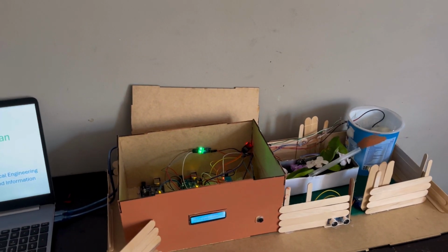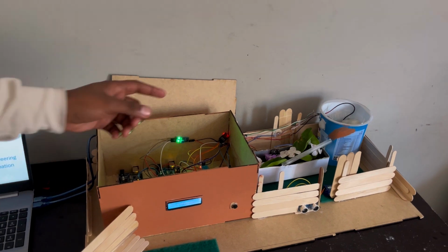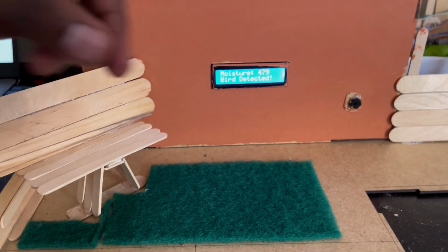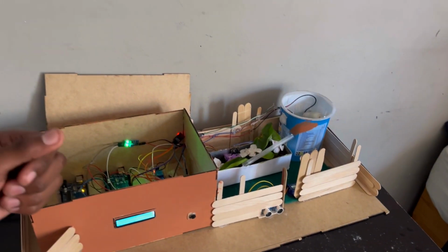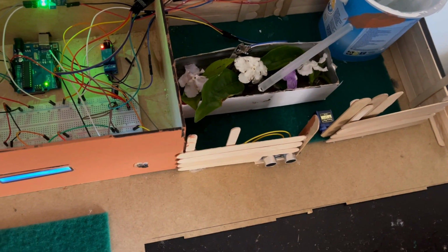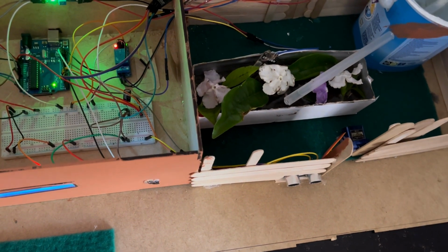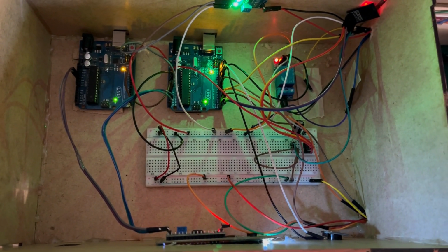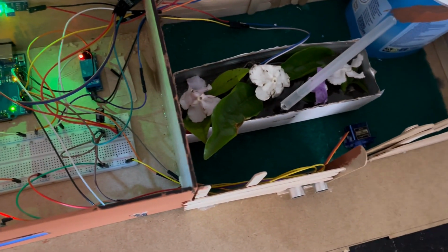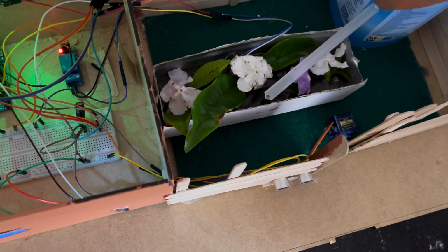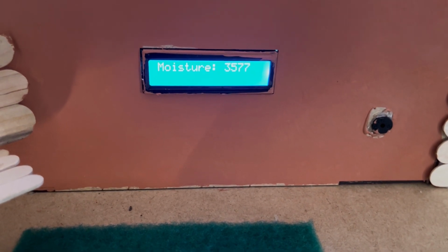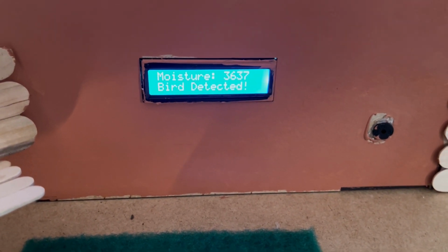We are going to go to my moisture sensor. As you can see, it is now below, at 479. So we're going to water it. As I've shown you, the relay is triggering and it's watering. As you can see, it is triggered. Let's look. There's no longer water coming out, which means it is moist enough. So the moisture is going up.